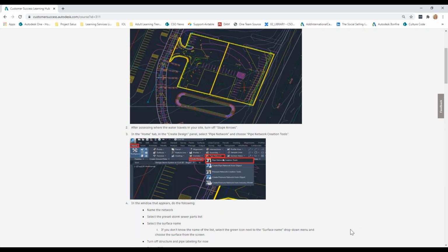I love that question. Thank you. All right, so John is asking the question, I'm supposing if we were to use Total Station to collect points and lines, it would be helpful to understand in general the minimum required to perform a reasonable design. Absolutely. And so I assume enough to model the curb line, existing intersection slopes, and then specific constraints such as the building entrances and or other untouchable monuments.